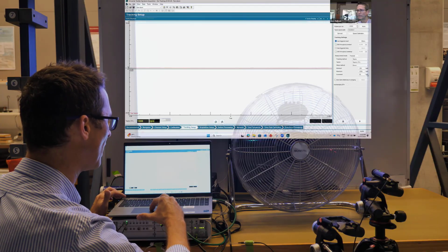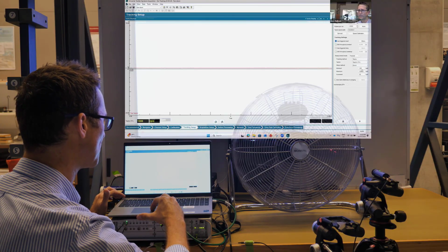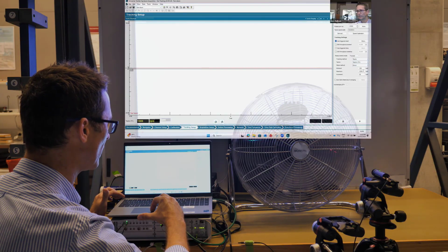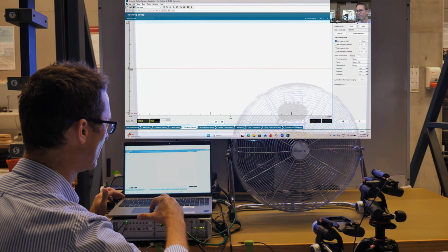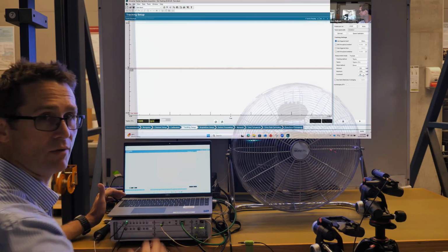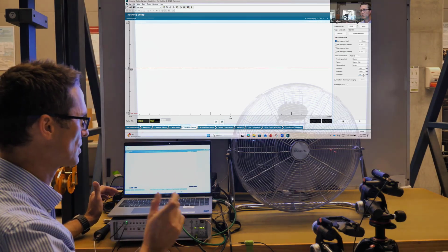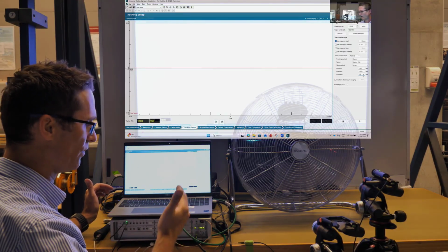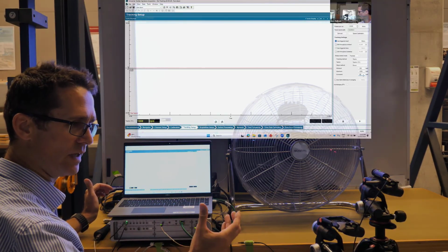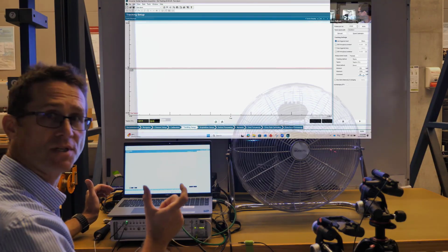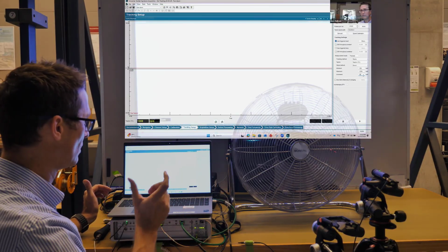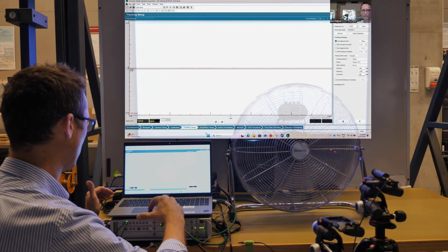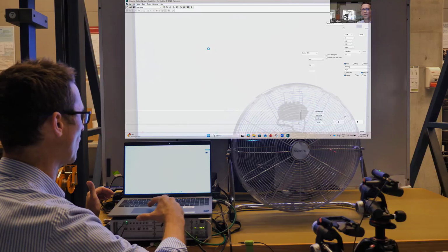And so what I've defined here is to do a rundown measurement from 1250 RPM to 100 RPM in 50 RPM increments. Now that requires that the rundown is sufficiently slow that at each of these increments in RPM, at 1250, 1200, 1150, 1100, I've got enough time to create a new spectrum with the required resolution, and I've defined that information in the acquisition setup sheet.